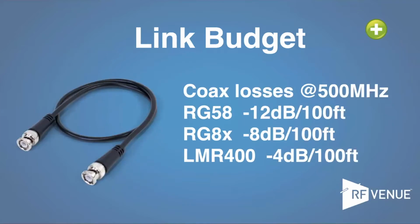And now you've got to connect that antenna with a cable. Coax losses, again, are figured at 500 megahertz. Whatever wire you're using, you can go to the manufacturer's spec sheet and you're going to see the loss. Typically, they show the loss per 100 feet or per 100 meters. It's easy to calculate.